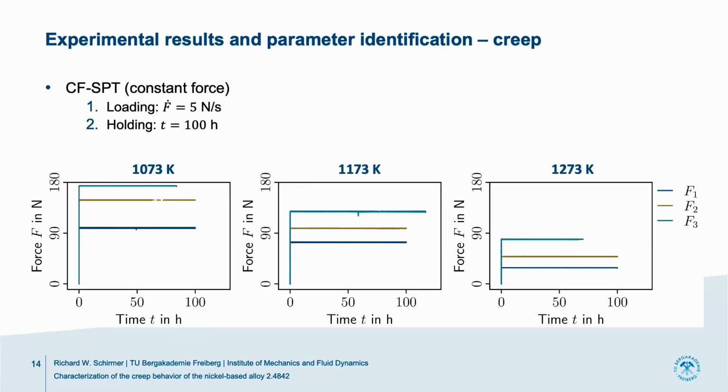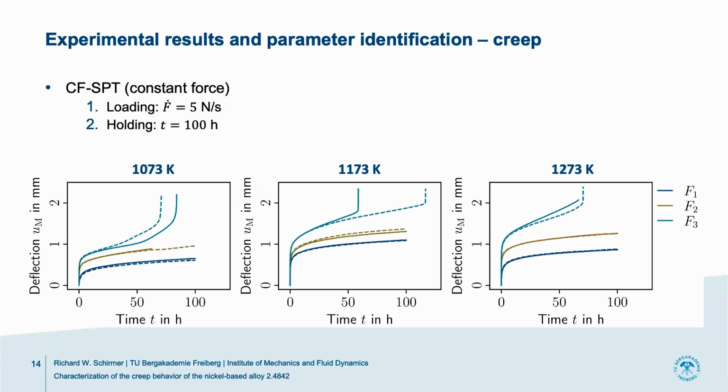Let's switch to the creep tests. They're not constant stress or constant stress state inside of your specimen, but instead they are constant force, because that's the only thing that we actually can do in small punch test. And our goal is that we do the test only to 100 hours because we're limited in testing time, and reload the specimen with a constant force rate.